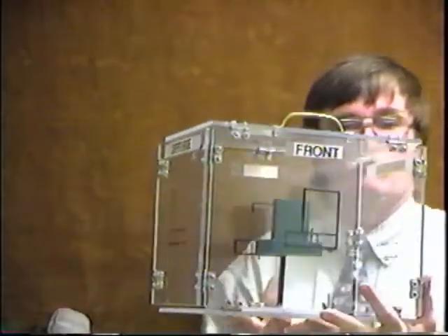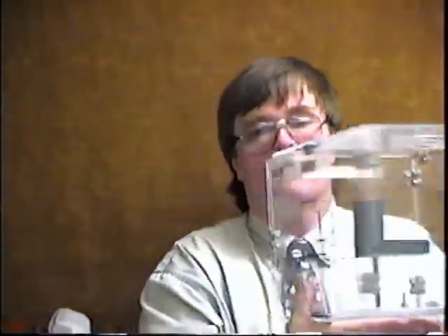The last thing, orthographic projection with the 6 normal surfaces. They define the horizontal plane for the top and the bottom. They define the profile plane for the right side and the left side, and they define the front and back of the part. As we see here, there's our front of the part, there's the back of the part. That would be our z direction accordingly.